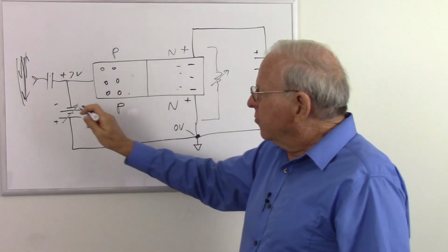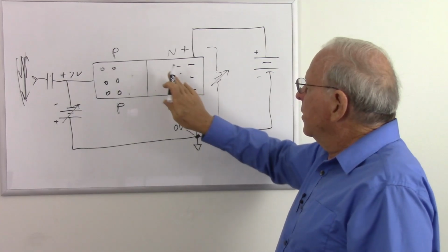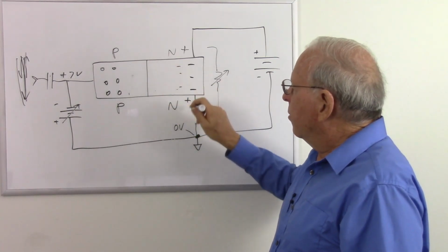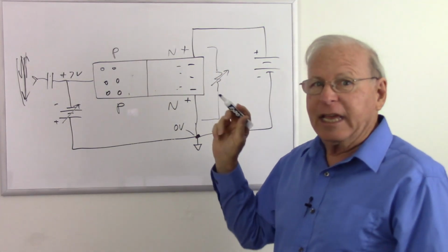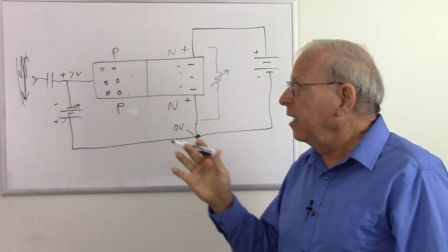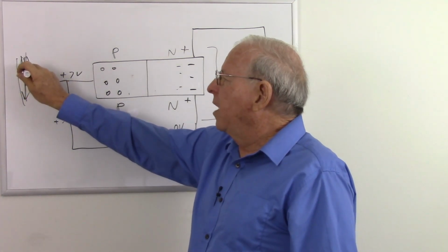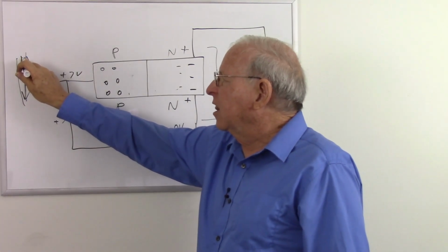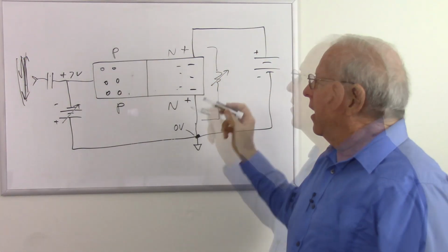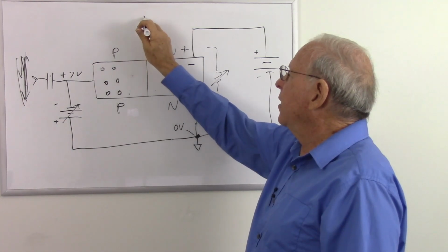less conductive. So with this arrangement, where the N-type material is where my conducting channel is, which is called an N-channel FET, as this goes more positive, it conducts more. As this goes less positive, it conducts less. And I'll just draw the symbol for that right here.